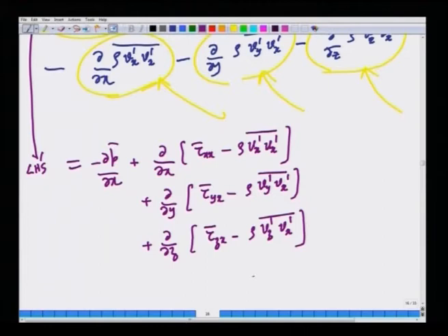Okay. Now this appears like again the same Cauchy momentum equation, except that you do not have just the mean stresses coming from Newton's constitutive relation, but we also have this extra contribution. These can be interpreted as stresses because they have the dimensions of stress and they come in the same way as the divergence of the stress. So, these have the same meaning as stress. These three terms are called turbulent stresses. These are the stresses that are caused by the turbulent flow.